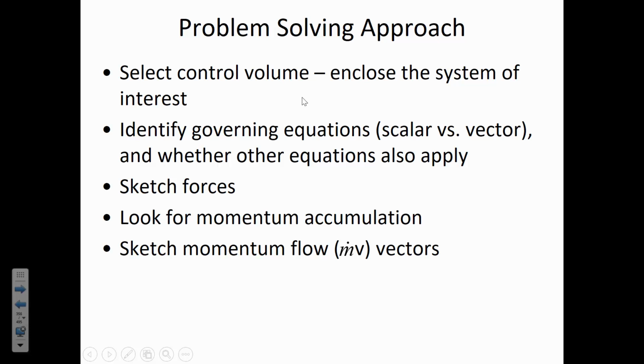The momentum equation is sometimes a little bit tricky because you won't necessarily be given where the control volume is in the sketch or in the problem statement. Sometimes you have to decide where you should put the control volume. And the way that you know how to do that is you just draw the control surfaces so that it encloses the system of interest. For example, if you have a jet of water that's coming in contact with a plate, and it's deflecting the water as it does that.